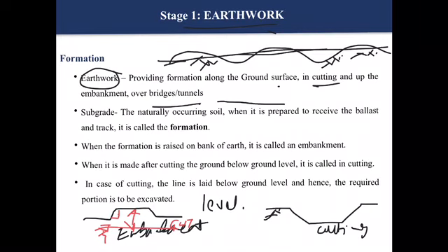So we have to ensure that proper drainage will be allowed in the railway track section. Similarly, if the alignment is taken along the cutting, then lateral drains have to be provided adjacent to the track, so that any water which comes into the railway track, it can be surface water from the adjoining land, any source of water entering into the formation level will be diverted away with the help of these drains. So that has to be ensured when you take your formation level in the embankment and the cutting.